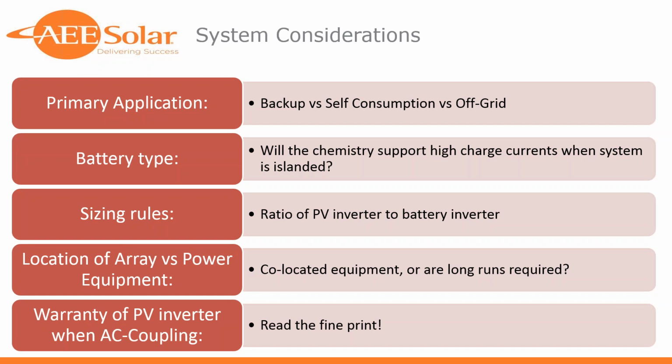So in that instance we talked about a few slides ago, when the system islands and the loads are much lower than the PV array is producing, even when you've got a curtailment-enabled solution, the PV inverter cannot respond instantaneously, and that current has to go somewhere. And in most cases, it's going to try to go into the battery. If that trips the breaker in the battery, you've got a battery you've then got to go manually turn back on again, which is never a good thing in terms of customer satisfaction.